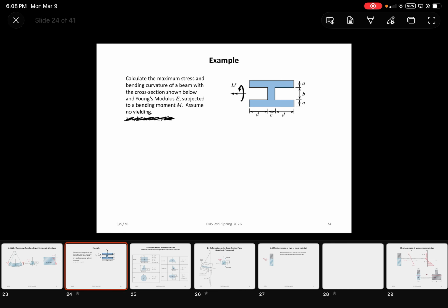All right. How many of you wasted your time calculating the centroid? It's a symmetric shape. It's an important thing to note. If it's symmetric, the centroid, if you looked carefully enough, y bar, is just going to be at (a plus b) divided by 2. Everyone sees that, right? The hard part is getting the I term.